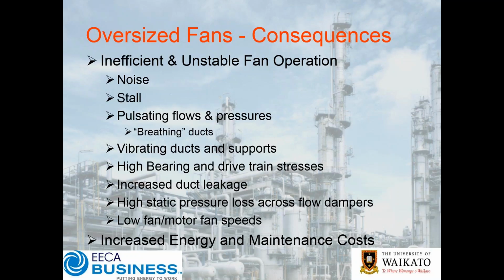Generally, if fans are oversized, we end up having to dampen back the fan to put the pressure drop up to restrict the flow, which means our static pressures in all our lines can be a lot higher. We end up with high static losses across dampers. Our fan might be running at low speed. Our motor might be at low speeds, which then has impacts on the long-term life of the motor. Ultimately we end up with increased energy and maintenance costs.